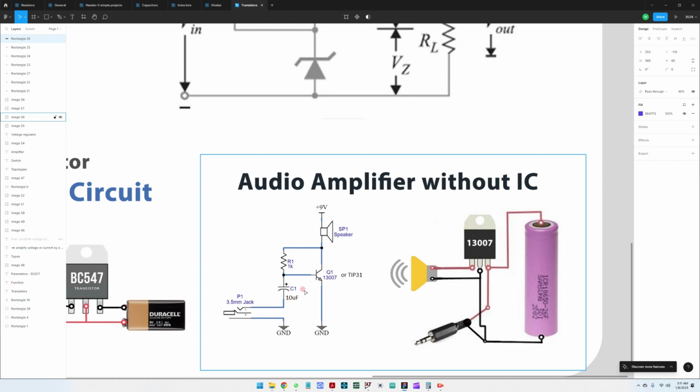It will pass through this capacitor here and then go into the transistor, which is then going to drive the speaker. And the transistor will use the amplification because these are power amplifiers, power transistors. They would have a much smaller beta. So they typically have 40, 50 times the input level. So here it would not be a problem to saturate the speaker through the signal.